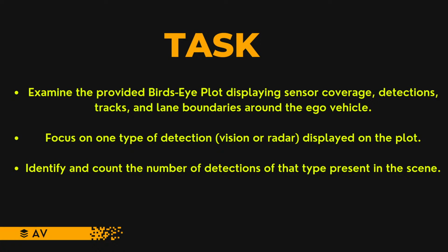So before we wind up the session, I will conclude today's session. Today we visualized the surrounding environment of a vehicle by using the bird's eye plot. We configured the coverage areas representing the sensing range of vision and radar sensors. By loading recorded sensor data, we plotted the detections based on that. And we also plotted the tracks of objects, including the most important objects also.